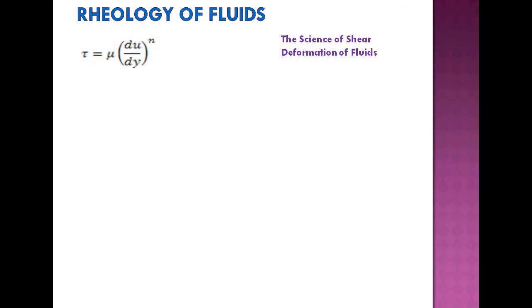Or we will put it in another way. There is a velocity profile, as we have seen in the previous lecture, from the solid body towards the free surface of the liquid due to the effect of viscosity. So the shear stress is developed due to this velocity gradient. We will study that. That is different for different fluids. That means it is a science that deals with shear deformation. If you compare butter with kerosene, the deformation under the action of an applied shear stress is different.